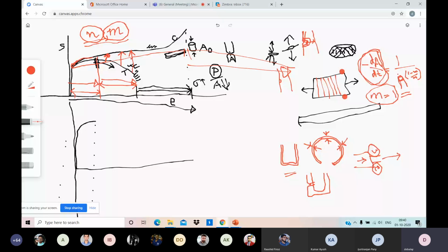something is there in compression which is not there in tension. You think about a compression test and you think about a tension test. Why the stress requirement? I am not talking about load by area. Stress. Even if you tell me true stress will be higher in compression. True stress, if you consider the area change, still that will be higher in compression. Why is that? So the negative and the positive dislocation may merge.